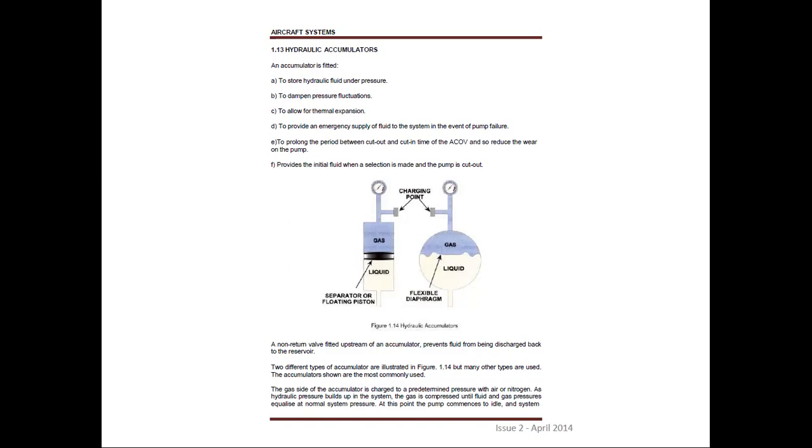The hydraulic accumulators function when there is no hydraulic power stored in the system. Like, for example, the aircraft is shut down. No pump will work, no engine running to energize the system. So, this is where the hydraulic accumulators come in.